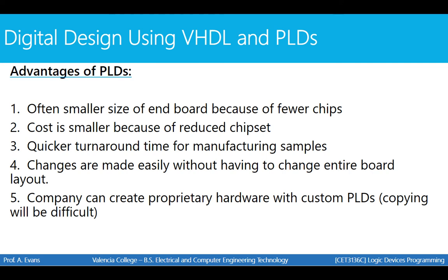Some of the advantages of a PLD: they're often smaller in size because of the fact that they have fewer chips. The cost is smaller because you have reduced chipset. There's a quicker turnaround time for manufacturing samples. And in my opinion, the best advantage of a PLD is changes are made easily without having to change an entire board layout.